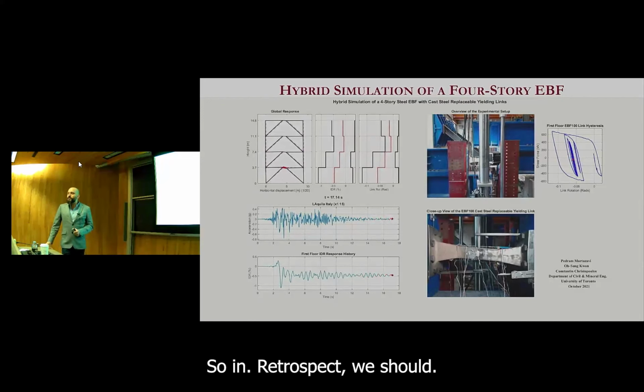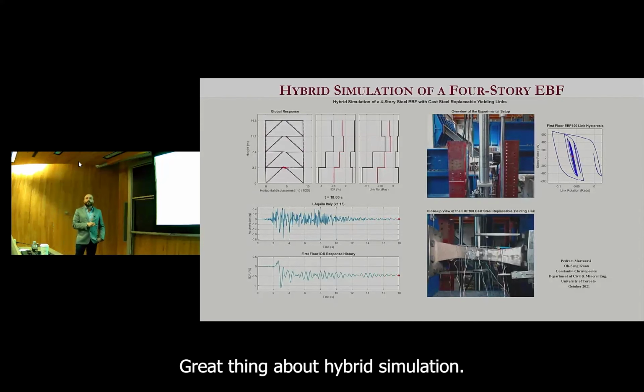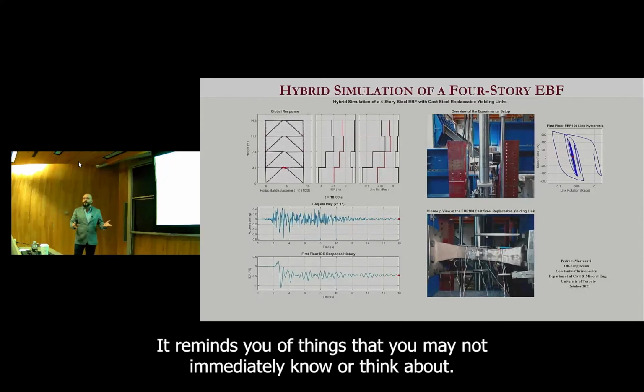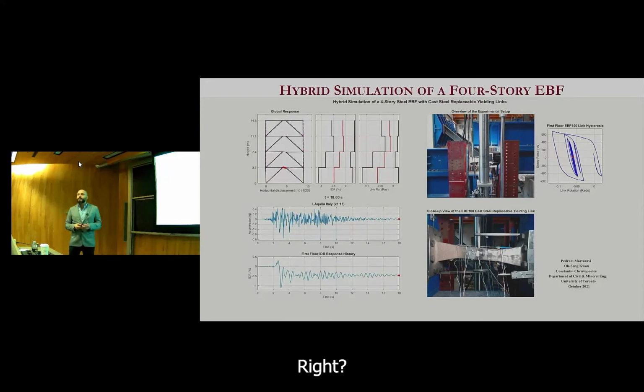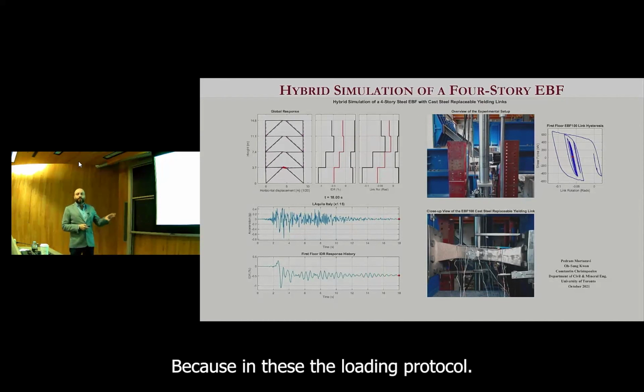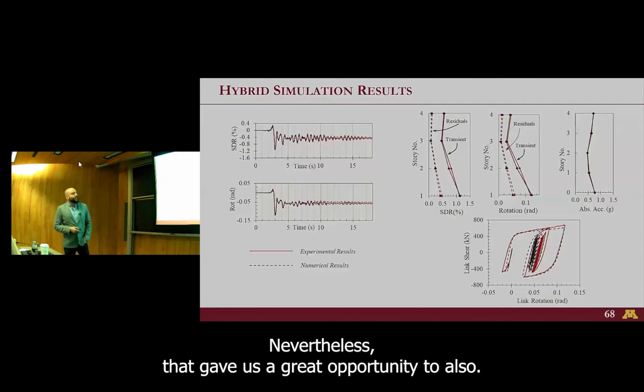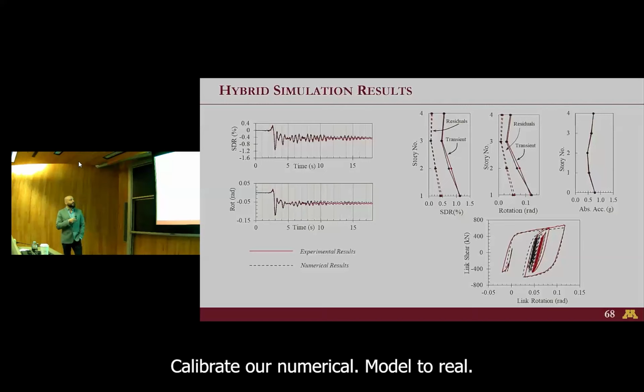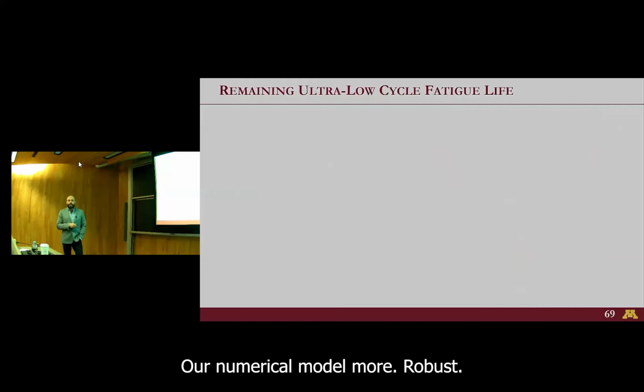So in retrospect, we should have known that, but this is the great thing about hybrid simulation. It reminds you of things that you may not immediately know or think about, right? Because in these, the loading protocol correlates to the earthquake. Nevertheless, that gave us a great opportunity to also calibrate our numerical model to real random loading histories, so it made our numerical model more robust.